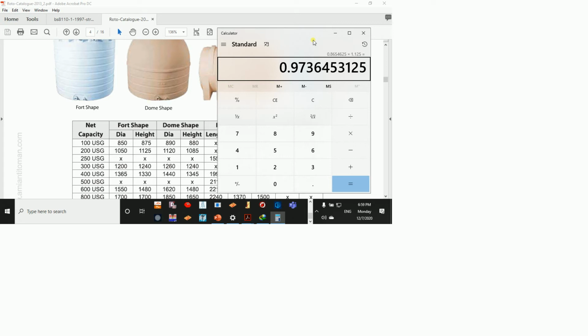For example, if we are talking about a flat slab system, we don't have beams. Normally we keep the loading of the walls on the beams, but in case of flat slab, we don't have it. So engineers are fighting on how to calculate, because I don't know where the client is going to put walls. Eventually he can go and just put a wall wherever he wants. We don't have that mentality of client, that if he has this room as a bedroom, at any time here in Oman he can change it to a store. So he might be constructing a wall anyway.